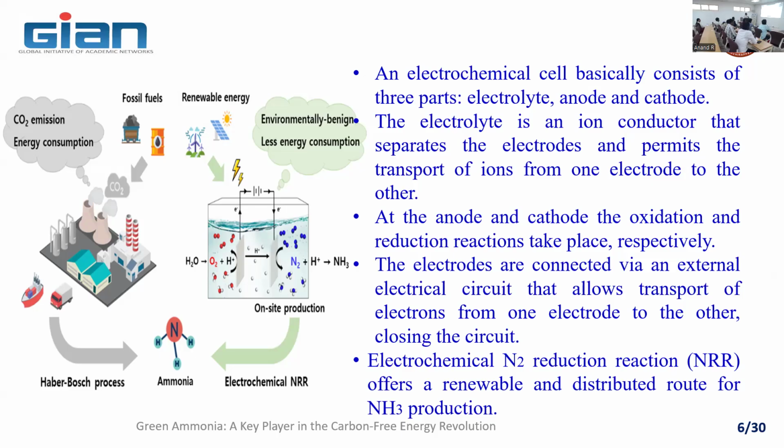Here the hydrogen will be sent into the system, and hydrogen ions will go through the electrolyte to the cathode. Electrons will be coming to the cathode via the circuit. Here the H plus is there, so you are providing oxygen into the cathode. So hydrogen, I can say, reacts with the oxygen producing water along with electricity.